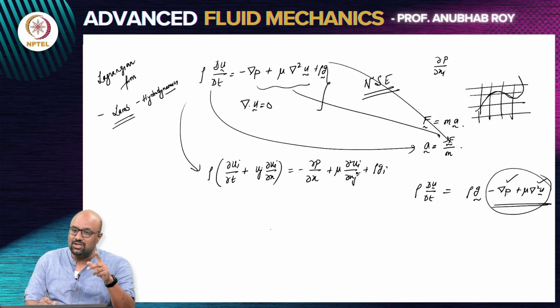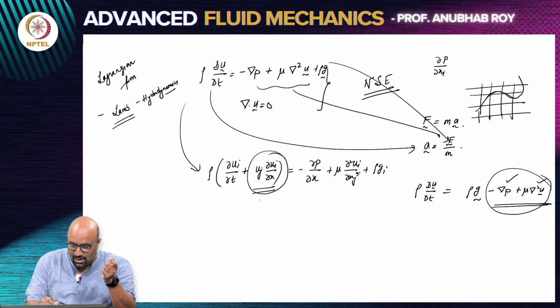So, that is a distinction. The constitutive relation is linear, but the final conservation equation that we have, the Navier-Stokes equation, is non-linear, and the non-linearity precisely comes from the advective term in your acceleration.